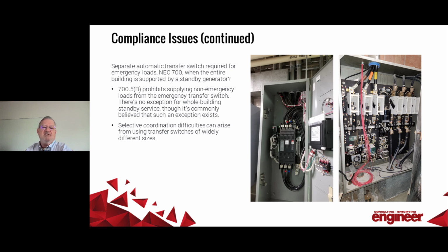In a lot of facilities, a small emergency system serves mostly lighting, and a much larger optional system will serve HVAC. And in order to get selective coordination between the optional system and a single generator breaker, it can be necessary to use a lot of smaller transfer switches to serve those optional loads.